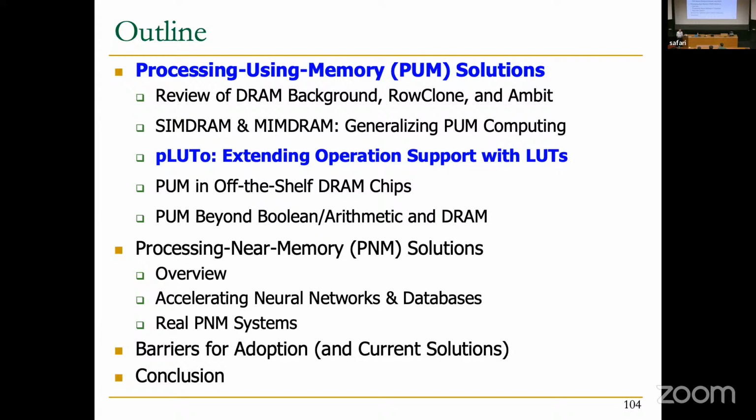So initially when we first proposed the SIMDRAM work, I think we were not so familiar with the blast effect of RowHammer. If you think about only RowHammer through the adjacent rows, actually what we are doing when we do triple row activation is a refresh, because we always activate and then we precharge.